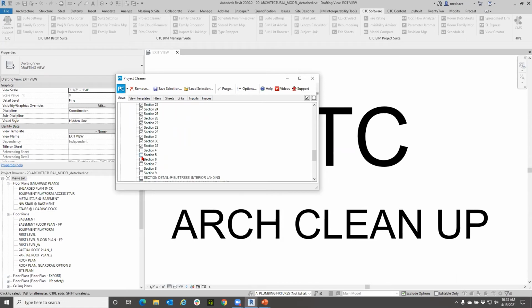So you can go through and run this clean. I can keep selecting for whatever. I can go down and also see, great, so those are those ones. What about renderings? Maybe these renderings shouldn't be directly in my project. They should be saved out and linked in, so they're not being referenced in my complete file size. They're just referenced wherever they are linked in and shown within that specific view only. So another good one would be all renderings. Again, save them out and bring them back in as a link. Sorry, a correction: not an import but a link, because an import would bring it back in as part of the complete file size. So a link is what I would do for the renderings here as well.